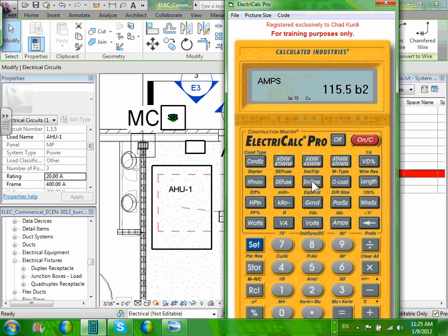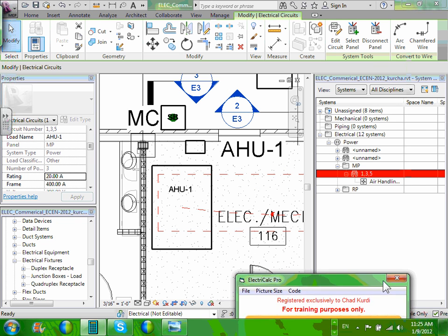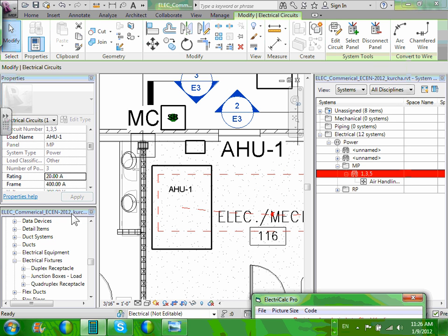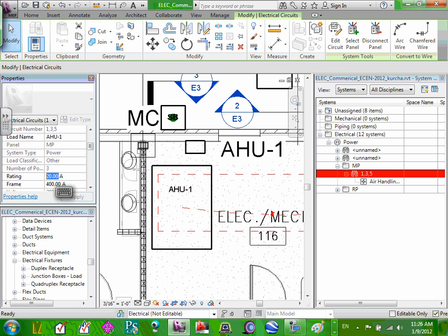So two ways. Either you're going to go to the bar, drink and cry, or you're going to go to the next standard size up. What's the next standard size up after 115.5? 120, there is no 120. If you don't know, you go to 240.6, guys. We know the next standard is going to be 125, because I know that between 110 and 125 there is nothing. So it's going to be 125. Everybody knows why 125? Based on this, 125, I'm just going to put it right down here. So I'm going to go to my circuit breaker here. What is it again? 125 amp.